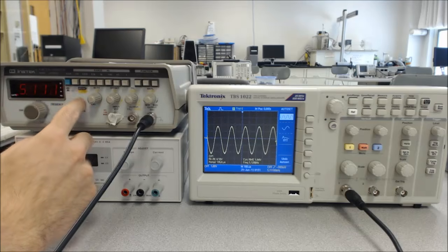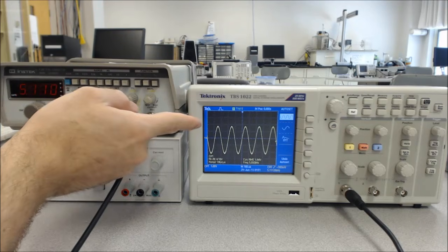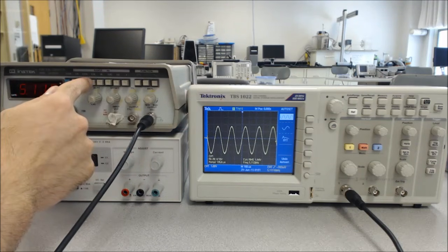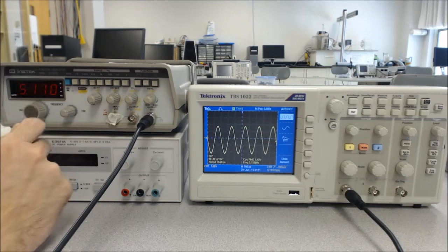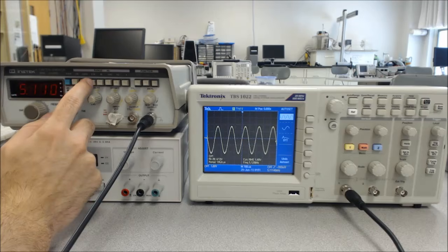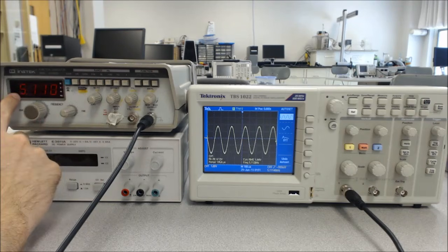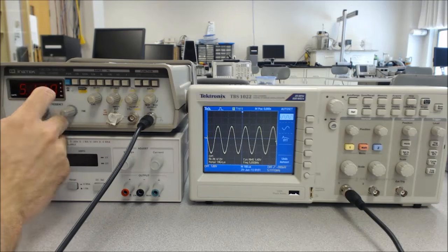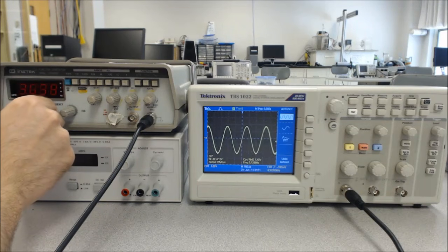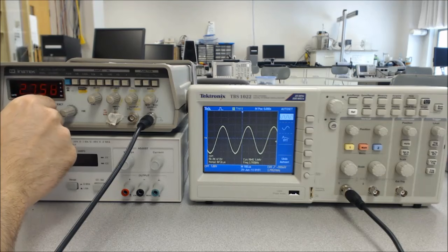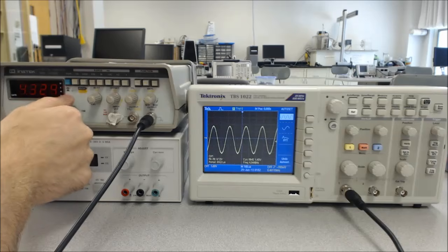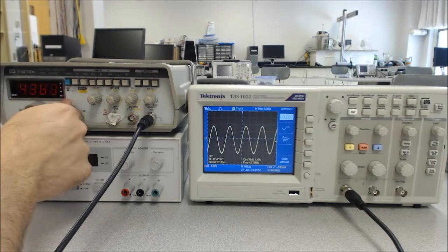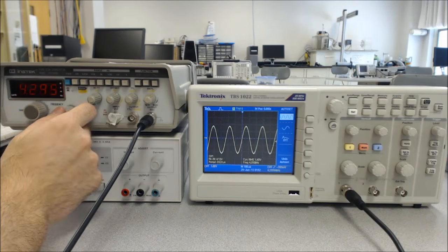But let's take a look over here at the function generator again. So we're seeing a sine wave that was produced by this function generator. And right now, if you look over here, I can set the frequency. I'm in the 10K range up at the top here. And this is telling me that I have a 5 kilohertz sine wave. So I could reduce the frequency to 3, or I could increase it with the coarse knob here. And if you want a finer resolution on the frequency, you can use the fine adjustment knob here.